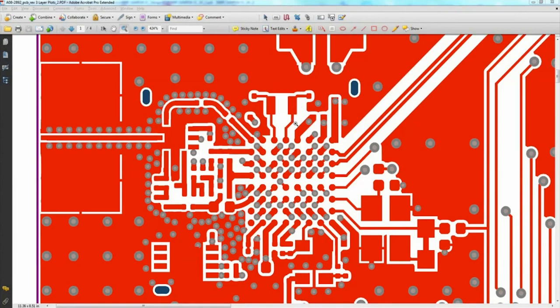Clock distribution and clock nets should have minimal delays. And here we have a very, very tight and direct routing with a crystal and an oscillator, all part of the RFIC, both for the low frequency up here, 32 kilohertz, and the 32 megahertz clock down here routed to the BGA. You want to reach low skew and implement delay time compensations if you do choose to use an external crystal driver to a part like this, which is not very common with this type of RFIC. But you want to, above all, avoid branches to reduce reflections. Use a clock driver to distribute the signal to every device and consider proper termination.